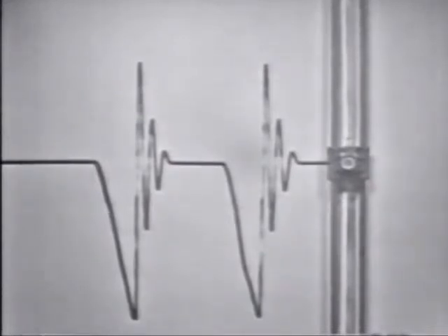Well, in this case, the action of the oscillator is gradually diminished by the friction of the slide, the friction of the pen on the paper, the force of gravity acting on the weight, and the resistance of the rubber bands themselves. In short, the diminished amplitude on the graph is caused by inherent resistance in the oscillator. Now, only if we overcome this resistance can we make the device oscillate continuously. And since this is a rather crude device, it has a large amount of resistance.